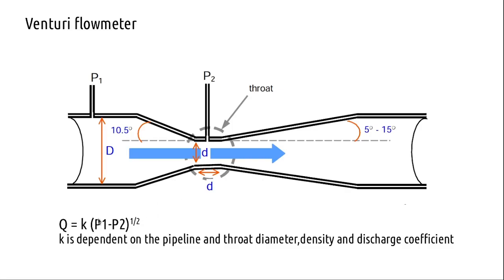A square law relation exists between the flow and the difference in the pressure at these 2 points. So in industrial meters, usually we make use of this principle of differential pressures. You record the pressure before the constriction and at the constriction, and that is where the pressure becomes minimum, the vena contracta. So pressure becomes minimum there, and you will have this parameter K for the particular type of Venturi meter, and you can make a measurement.